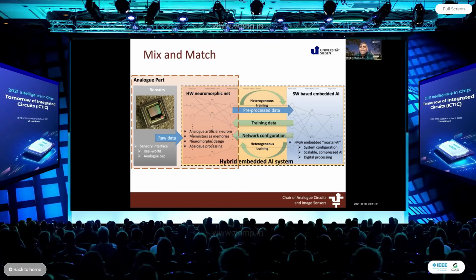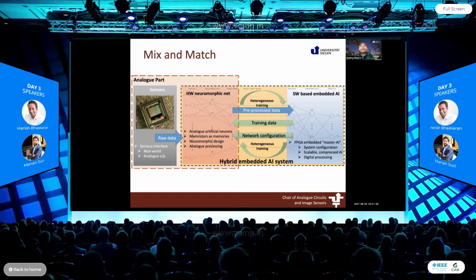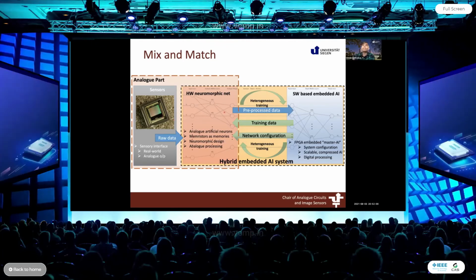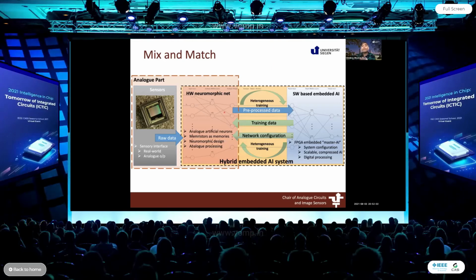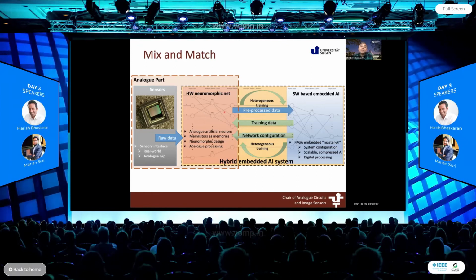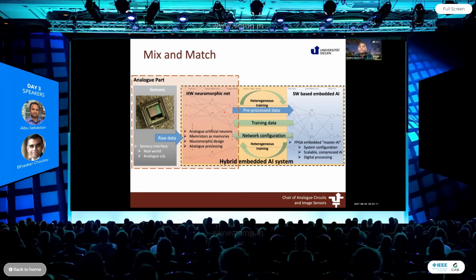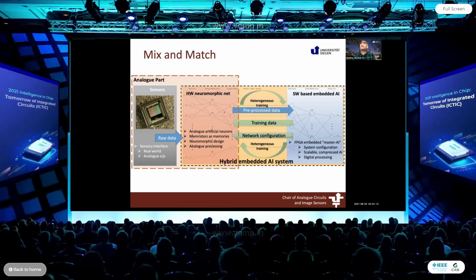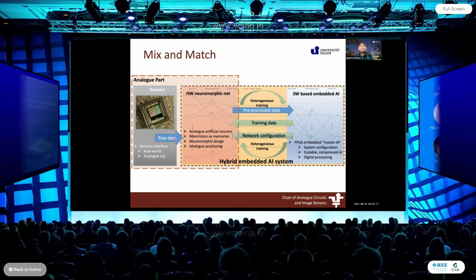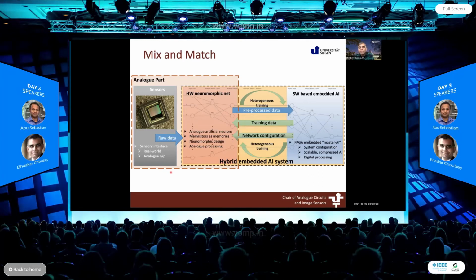Typical imagers have 8-bit resolution, and the better quality imagers would push the resolution to 12 or 16-bit. So if we can cut down the resolution requirement, and even if we increase the area, then our overall power requirement of the neural network will fall down. So that, I believe, is the message from ICTIC, that this is the arena in which we should progress, rather than designing pure analog neural networks or pure digital neural networks. How to combine these two together with the sensory output would be the key question in future.